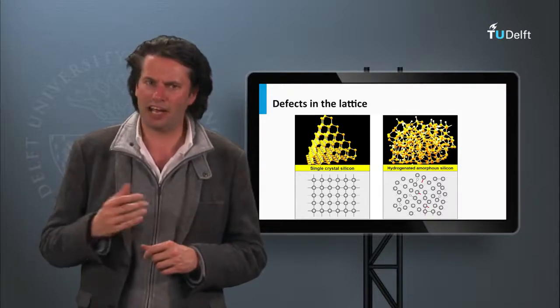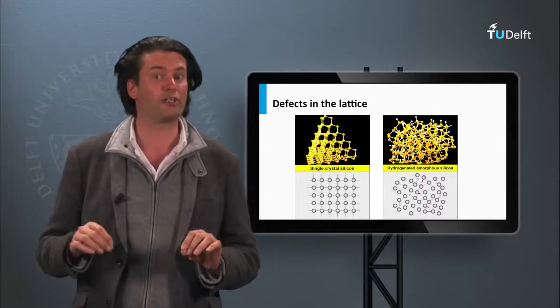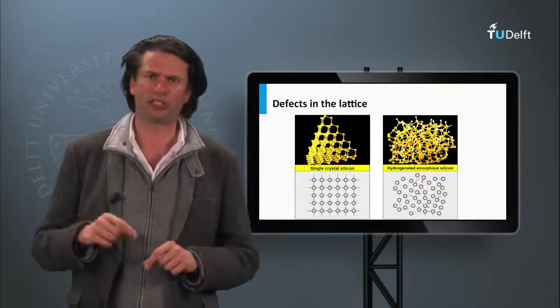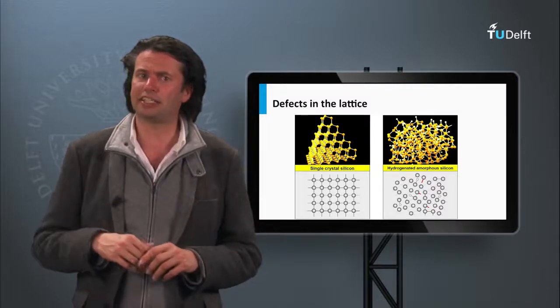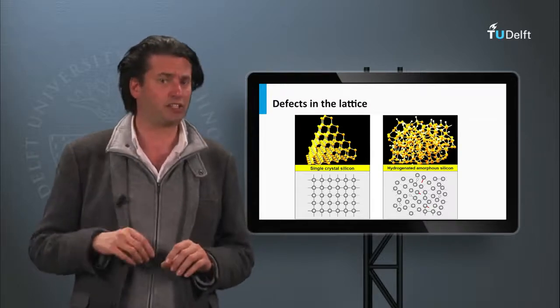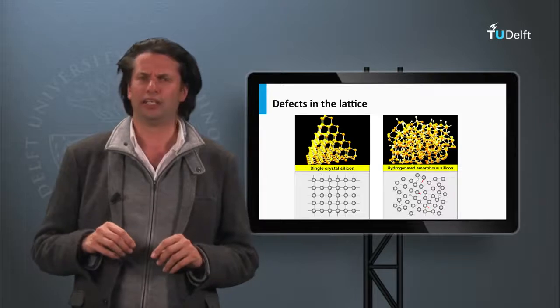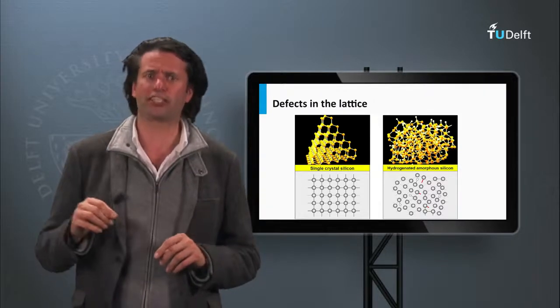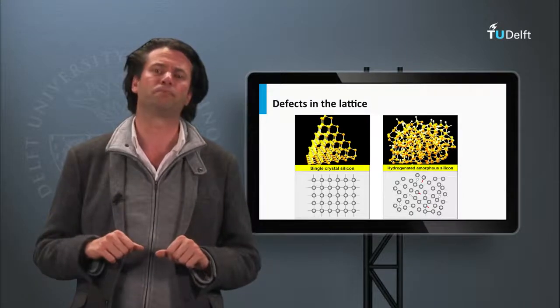This means that the lifetime of the light-excited charge carriers is limited by Shockley-Read-Hall recombination, which controls the diffusion length. The recombination is so high that the diffusion length of the charge carriers in hydrogenated amorphous silicon is only 100 up to 300 nanometers. This means that the transport of charge carriers in a thick absorber layer cannot rely on diffusion.